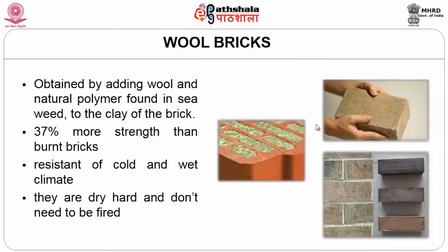So what happens by adding this is 37% more strength than burnt bricks. If it is not going to be burnt, the fuel efficiency increases and the consumption decreases. It's resistant to cold as well as wet climate. They are dry, hard, and do not need to be fired. So if these bricks don't need to be fired, we are actually saving a lot of time as well as energy. And because they are suitable for varied types of climatology, it is also very good.